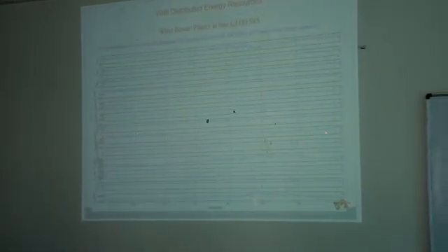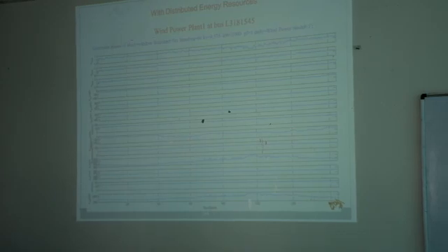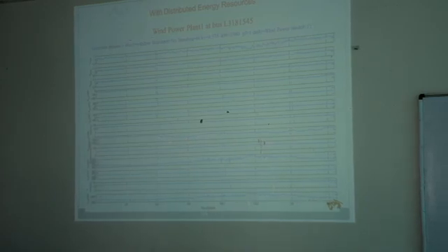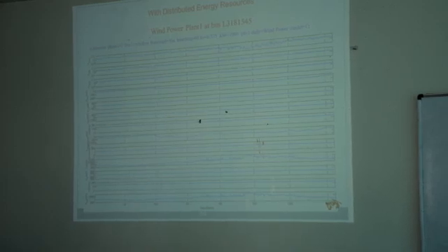Then you can notice this is the power generation through wind power plants. It's a negative power. According to convention, if you are injecting the power into the node, it should be negative. If you are absorbing the power through the node, it is positive as per our convention. So that is negative. It's 1 megawatt according to the mean wind speed, and you are receiving that much power.